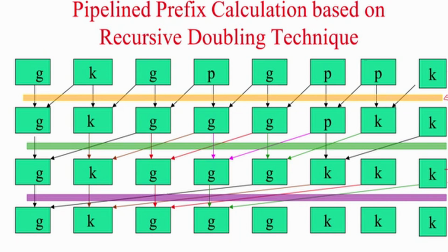When the first pair of numbers are in stage 3, the second pair of numbers could be in stage 2 and the third pair of numbers could be in stage 1. The registers or the storage I have put will isolate these stages so that some computation happening there will not come to the next stage, because the registers get updated only on the clock pulse, right. So, I hope you remember what is a register, flip flop and registers, right. Okay.